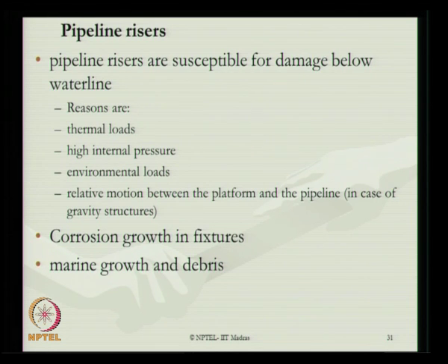Corrosion growth in fixtures is very important to be assessed for material, especially in case of joints. Marine growth and debris again becomes a very important area because they prevent access for inspection as well as NDT methods to be applied on buried pipelines in water.